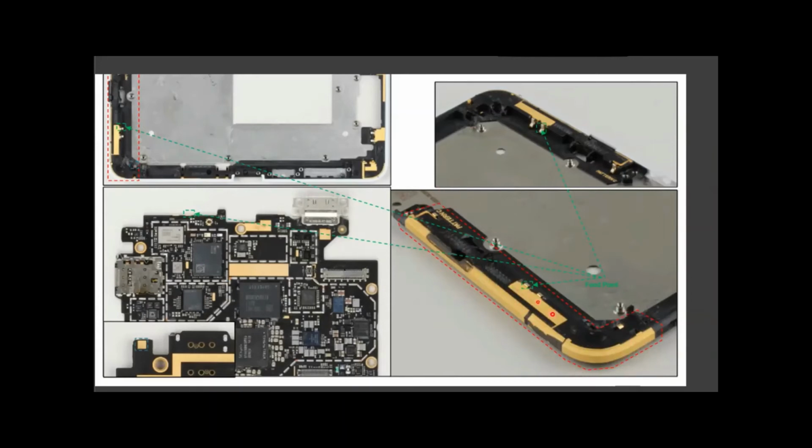So this antenna is a double coupled loop antenna. It has a feed mechanism here, a little short monopole-looking thing, and there are two gaps either side, which is effectively capacitive coupling. So I'm coupling some energy here, and this is grounded at this end, and that has a tuner at this end. You can see by the length here that this side is probably the longer 700 to 960 band. Then there's the ground point here with another tuner and a short element, and you can probably deduce that it's the higher frequency of the cellular band.